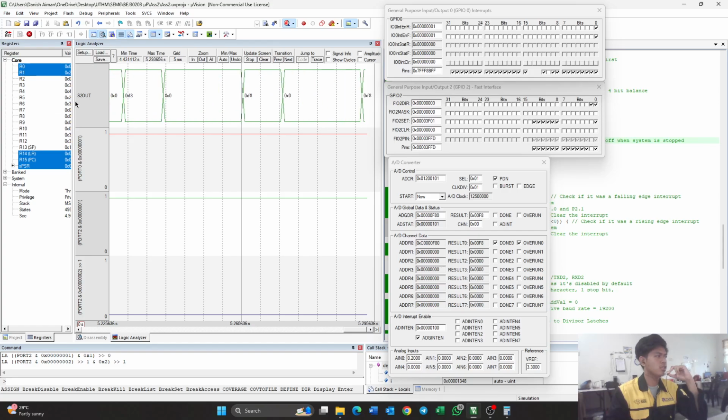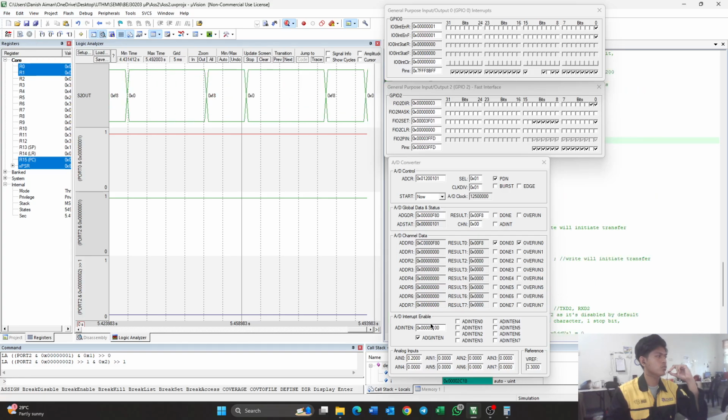So let's try the next value, which is over 80 degrees Celsius. I will choose 95 degrees Celsius, which will make the microcontroller turn on the cooler.